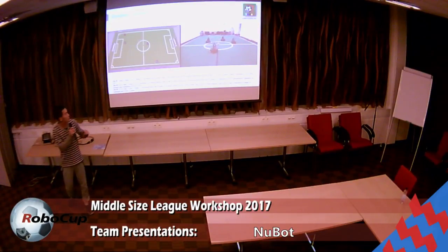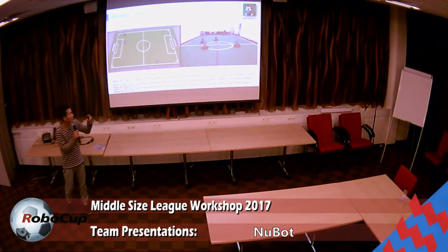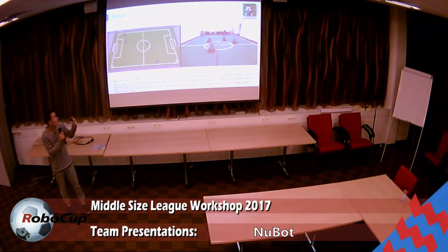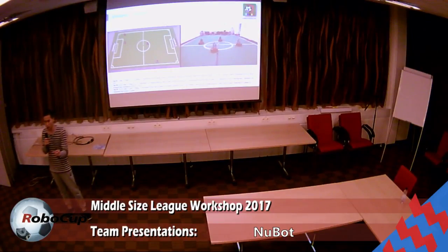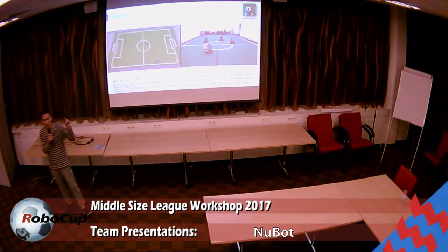So in this research you can see the soccer ball as an enemy. It's an enemy that we try to enclose with the robots, to surround the target and keep it from escaping. You can see that the spacing between each robot is changing. It tries to simulate the situation when different robots have different kinematic abilities. Some robots may move slower than others, so we try to decrease the spacing between 2 robots so that they can compensate for some deficiencies in their kinematic abilities.